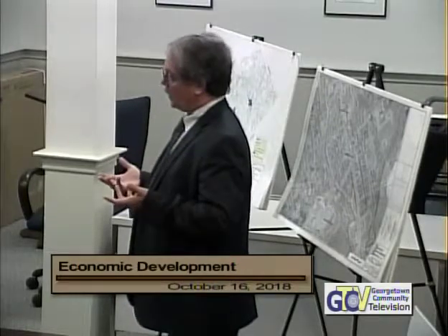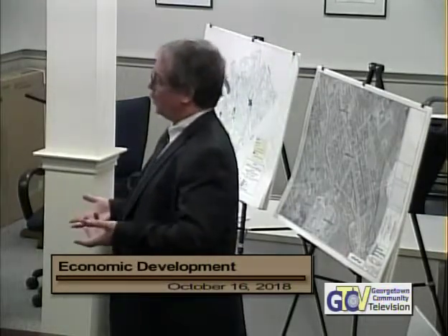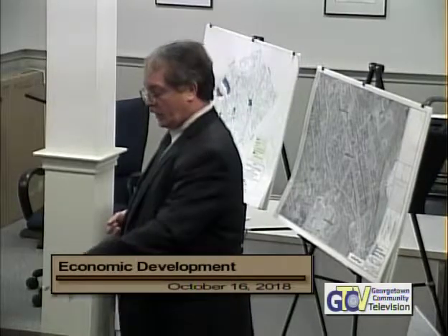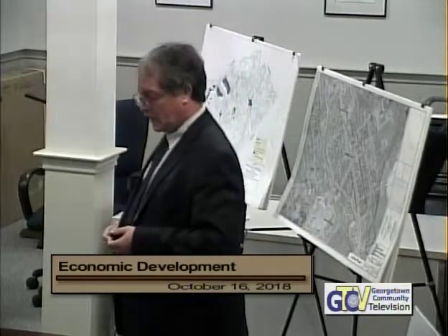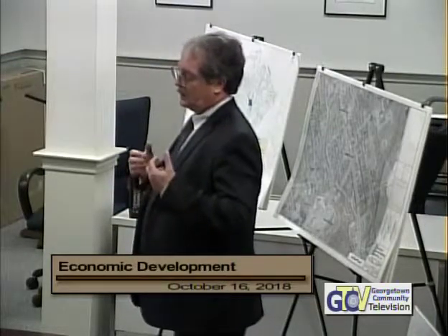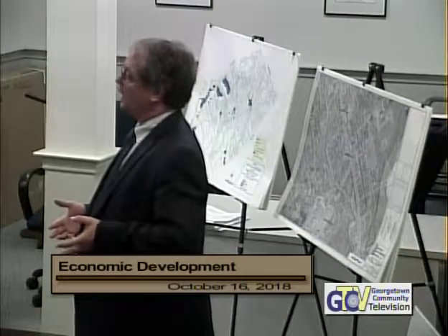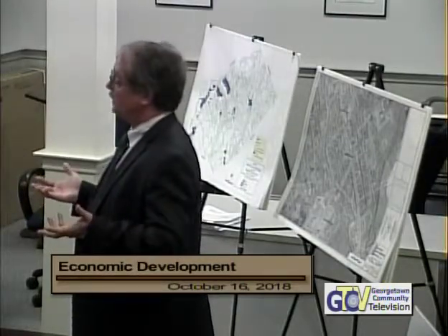A lot of the lands within the town have very shallow groundwater tables. That's a problem relative to subsurface disposal, because to permit a disposal area with the state, part of the process is groundwater modeling and projections of the groundwater mound that would be induced by loading the land with the wastewater after it's been treated. So we generated a couple of curves based on different criteria: low transmissivity mounding and high transmissivity mounding, which is basically the permeability of the soil. We're trying to bracket it, given these conditions, to determine how much area we need to comfortably put in a system.